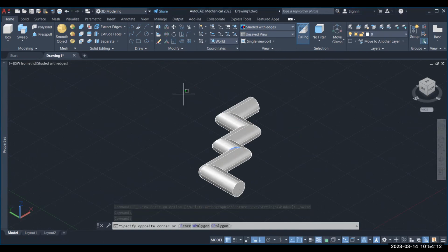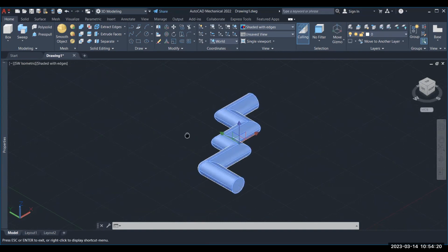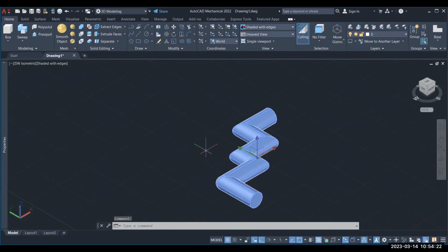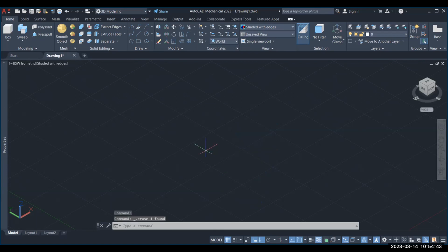Do you know blue selection? What is blue selection? What is blue and green selection? Yeah, if it cuts partly any object also, it will get selected. But blue, if you want to select anything, entire thing has to be selected, covered by that blue space, then only. Okay. So when you have to use blue, when you have to use green, based on your understanding and practice, will come to. Okay.